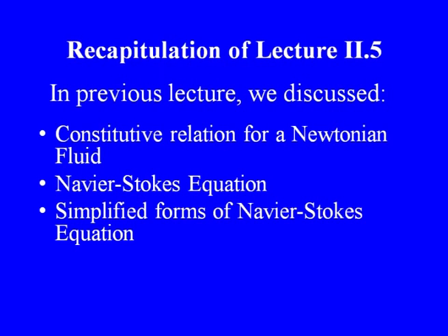We started off with a discussion on constitutive relation for a Newtonian fluid, for which stress and strain rate tensor are linearly related, and based on that simplified relation we obtained our famous Navier-Stokes equations. We also derived simplified forms for Navier-Stokes equations for specialized cases, for instance incompressible flows, which gives us a much simpler equation, and we had a look at the case of inviscid flow, which gives us the celebrated Euler's equation, and we looked at one specialized case which we call creeping flow equation.